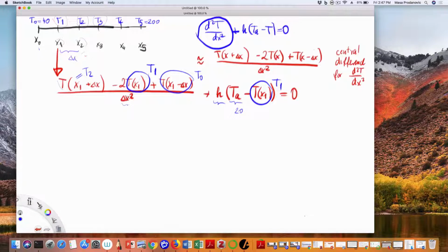And I'm going to get 3 more. Do you see where we're going? At the end, we're going to have 4 equations we're going to solve for T1, T2, T3, T4. And once we do, we have the temperature distribution we were looking for at these 4 discrete points. If I wanted to solve this at a much nicer, finer resolution, not just every 2 meters, but a little better, then yes, I would solve it with smaller delta x, and then I would just have a bigger system.